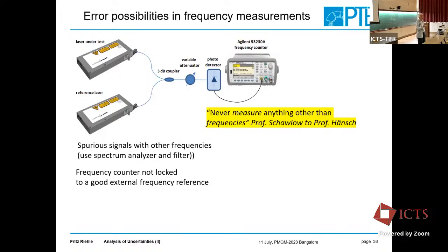You could put in there a Josephson standard, as I have shown yesterday in the evening, or a rubidium clock, or you could also use the frequency transmitted by PTB's long wave transmitter, or anything else you are aware of that can be used to stabilize your oscillator so that it gives you a well-defined frequency.